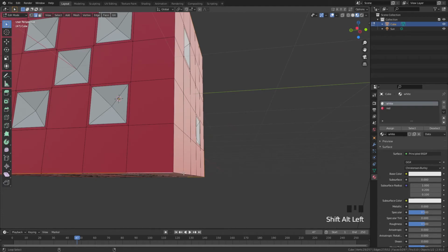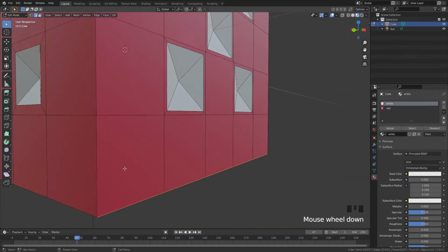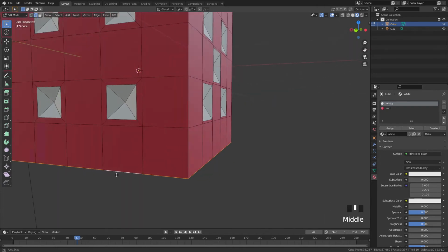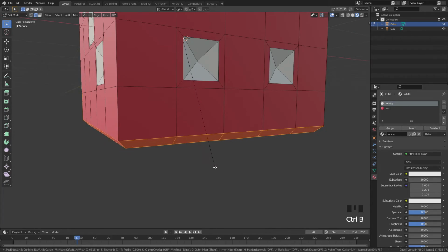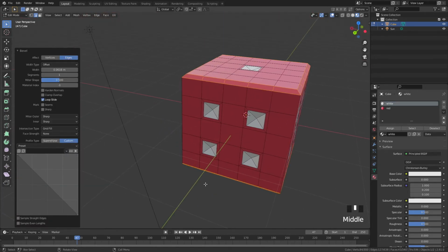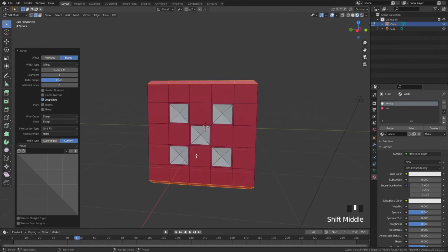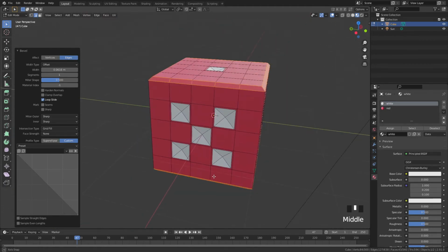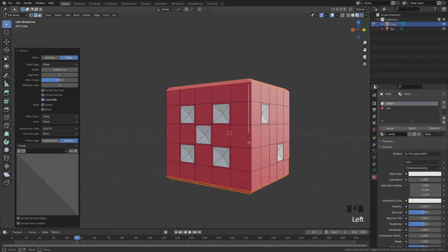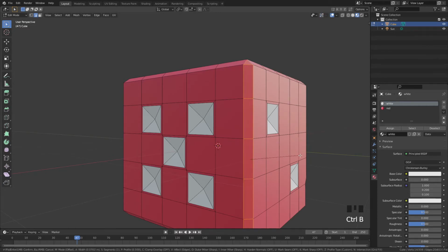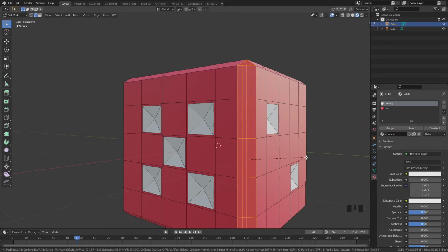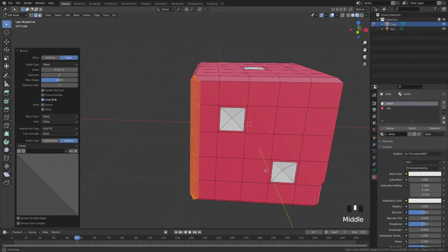Alright. I will choose all the lines here. And this one. Okay. Very weird. But now we understand what bevel is. If we want to move this here, Ctrl B again. This time, scroll up with our middle mouse, then it becomes smoother.